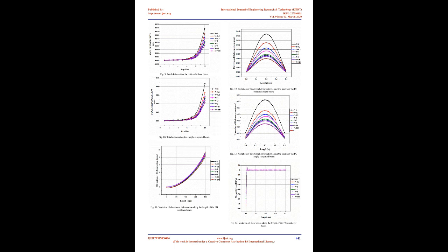boundary conditions. It is very clear from the figures that the transverse displacement is maximum for metal-rich FG beam and minimum for ceramic-rich FG beam, as we know that deformation is inversely proportional to the Young's modulus. Metals have lower Young's modulus compared to the ceramic. The functionally graded beam gradually becomes ceramic-rich from the metal portions.